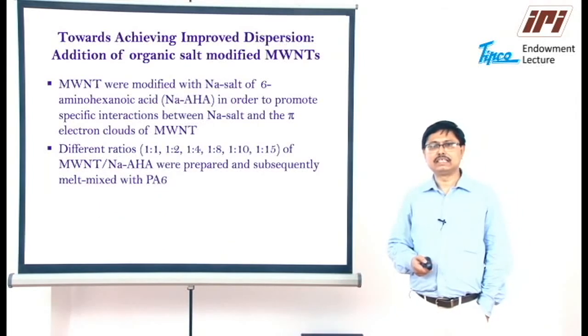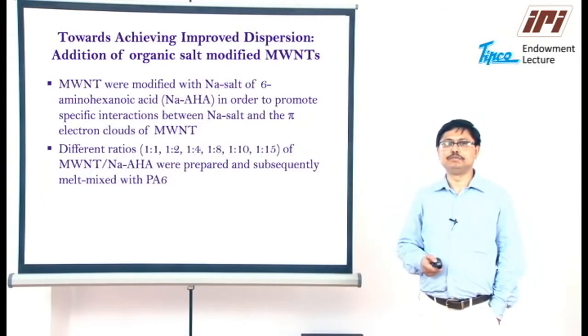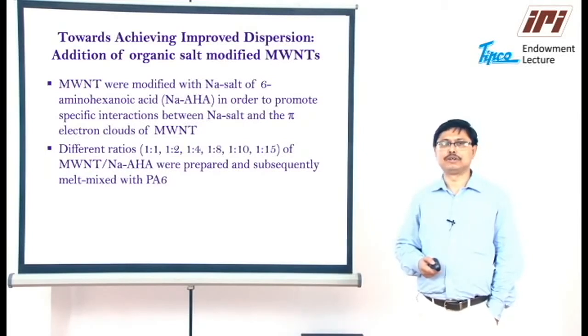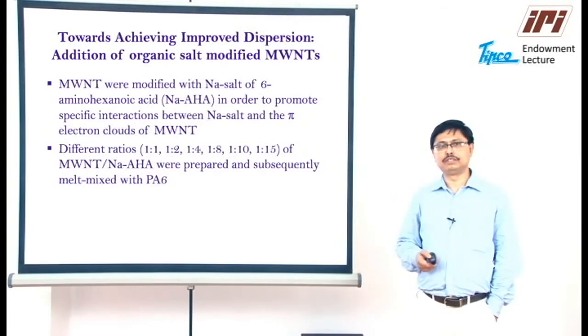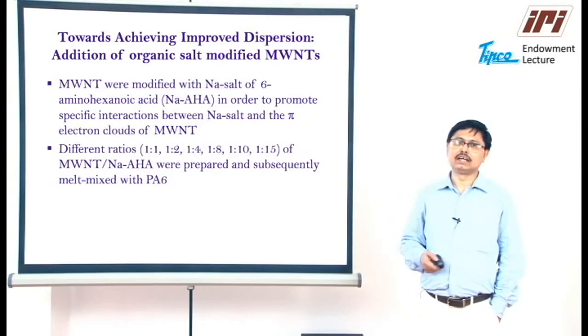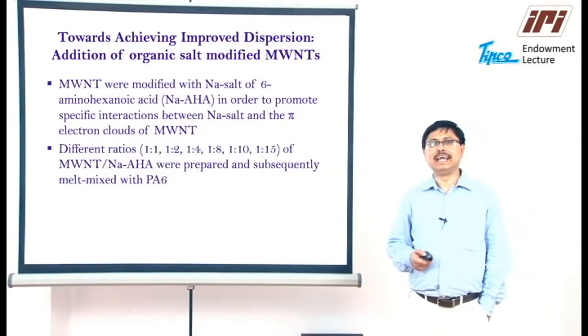Based on this observation, as far as the theoretical percolation threshold is concerned, multi-wall carbon nanotube based polyamide 6 matrix should yield an electrical percolation much lower than 2 to 3 weight%, based on the aspect ratio of the nanotubes and the theoretical percolation calculation as per Balberg, which suggests what volume % of nanotubes is required to form a 3D network-like structure if all the nanotubes could be individually exploited. Our experimental observation from the electrical conductivity measurements suggests that even the percolating structure involved aggregated carbon nanotubes.